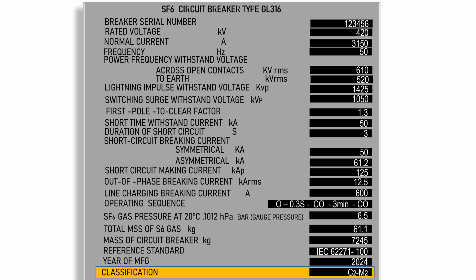Now, C stands for capacitive charging breaking current of a circuit breaker. It is also subdivided into two groups, C1 and C2. The C1 type indicates it has a low probability of restriking during capacitive charging breaking current. But the C2 class indicates it has a very low probability of restriking during breaking of such current. So the C2 class is more effective. Other parameters are not discussed here. So, all these are the parameters of a standard EHV circuit breaker.